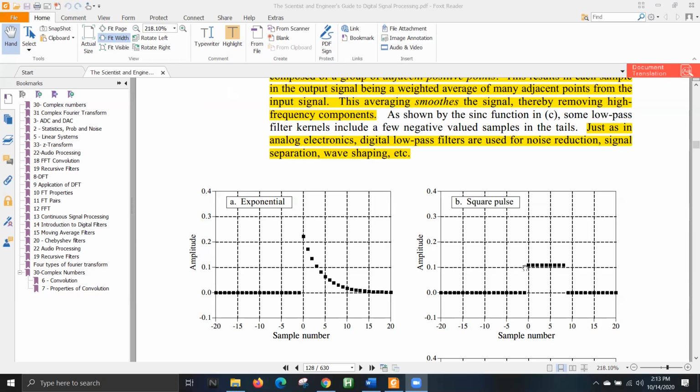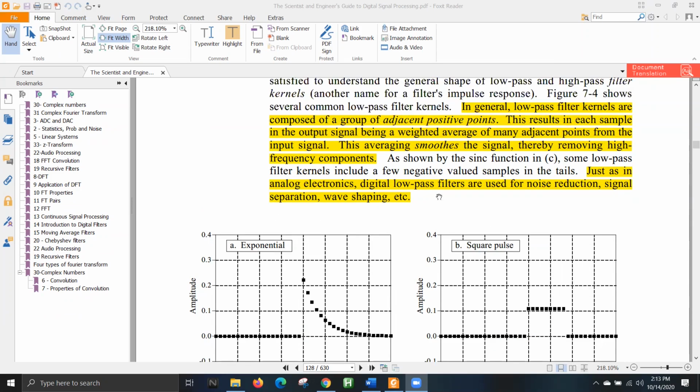And if you have these positive values extended, that means even from -1, if you start the positive values and extend it up to 15, then what you are actually doing is controlling the cutoff frequency. We do not need to know the details of how extending the positive values on the left and right allows me to change the cutoff frequency. We just need to know that the positive values define how much frequency I am going to allow to pass. If the positive value range is narrow, then the cutoff bandwidth is narrow. Otherwise, the cutoff bandwidth is extended if I extend the positive values.